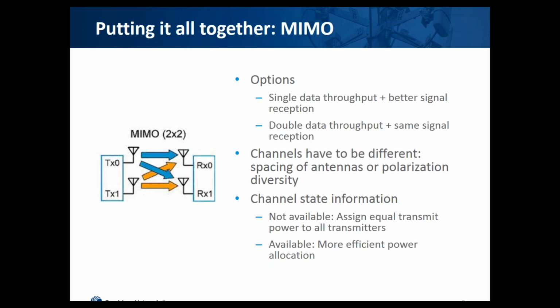So the vertical transmitter can send a stream of data to the vertical receiver, and the horizontal transmitter can send a stream of data to the horizontal receiver. We now have 2 parallel streams of data, which is similar to having 2 separate radios. Are the signals completely separate? Well, you can always have some crosstalk between the horizontal and the vertical paths, but having the 2 antennas connected to the same radio, you can clean up the signal internally, meaning that you can separate any residual interference.